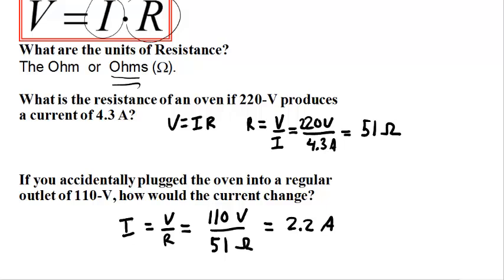Very few things actually need it. The dryer is one that comes to mind, and your oven. They even have special outlets so that you don't accidentally plug something else into it. There are other places in the world where their regular voltage is 220 volts, but here in Canada, in North America, it is generally 110 to 120 volts.